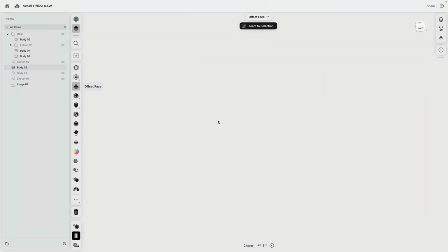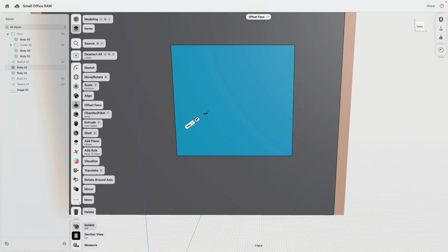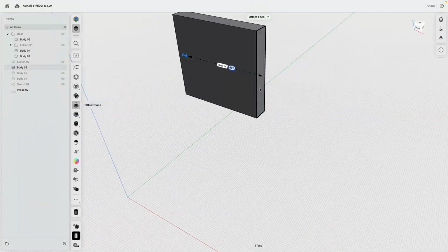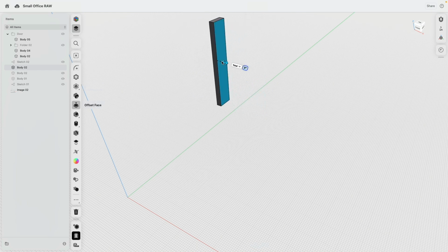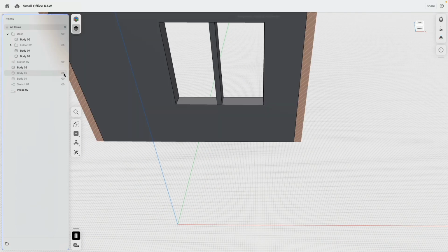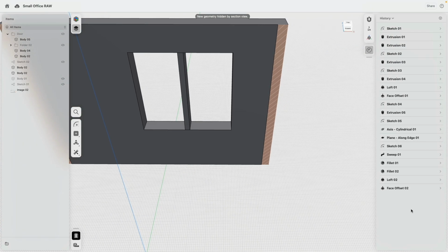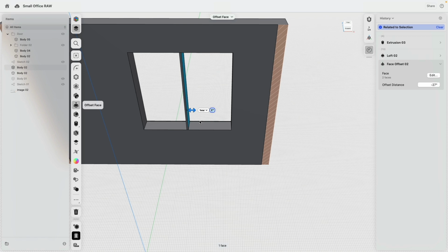So for example, I can select the top and bottom or left and right and do a loft. Then I'm going to maybe hide my wall and say, so these two make this smaller, 26. That is now 3 inches. Okay, so I shrunk this one down to 3 inches. That is okay. If I go back to here, maybe if I go 7, now this is actually now 1 inch. Yeah, 1 inch.